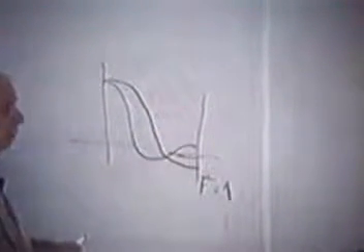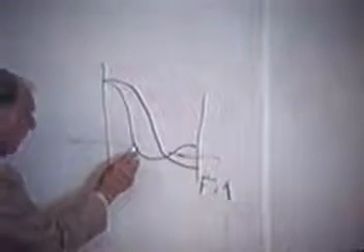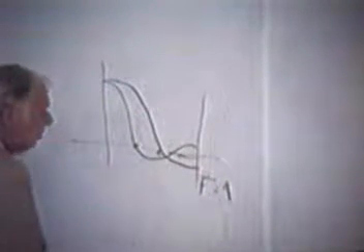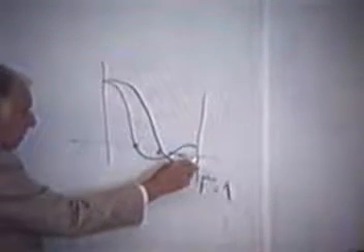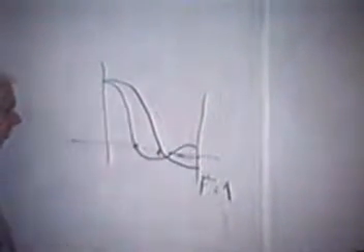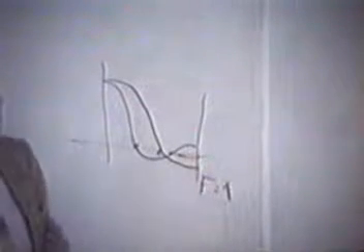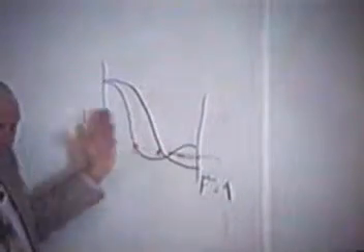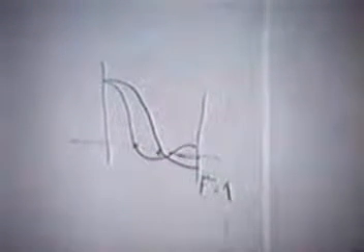Now, if I'm going to take one followed by the other, I'm going to get the product. I now have 3 zeros. And you can see the product there is going to be much less. It's going to be 1/15, something like that. So the product, smoothing by 3s followed by smoothing by 5s, is going to remove the upper half of the frequencies and leave only the lower half, which is what we call a low-pass filter. Very, very simple filter with very, very simple equipment. Just running average of 3 followed by running average of 5, and in fact the 15 is carried over to the last minute.